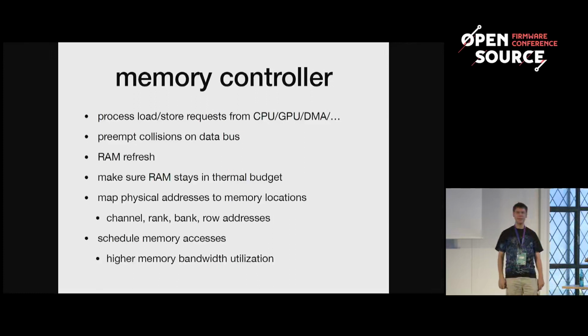So yeah, it has to schedule those commands properly. That never happens. It also has to take care of the periodic RAM refresh, because it's dynamic RAM. It only holds the ones and zeros in the capacitor, and over time those electrons go away from there, and so you have to periodically refresh that.